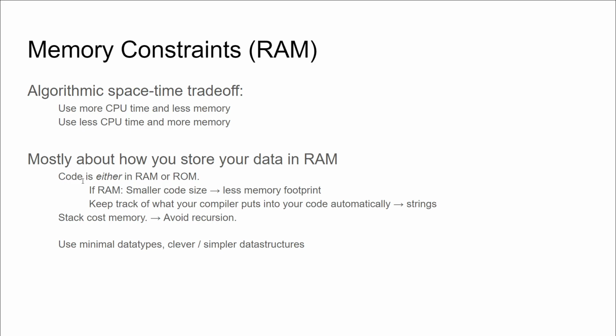Some platforms also store instructions in RAM instead of ROM. When they do, there is obviously less RAM to go around for everything else, so your binary footprint may really matter in this situation, as it leaves less RAM for the application itself. But when they don't, you can often put constants in code that is available through ROM, which then opens up more RAM for you.